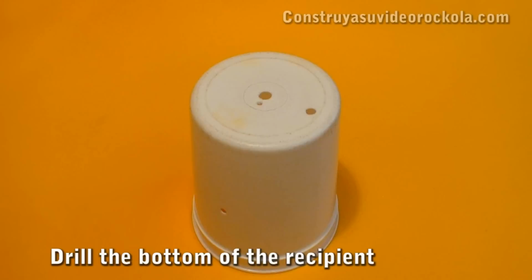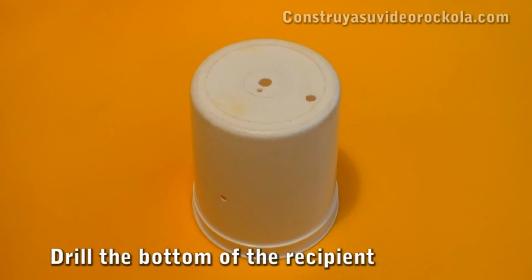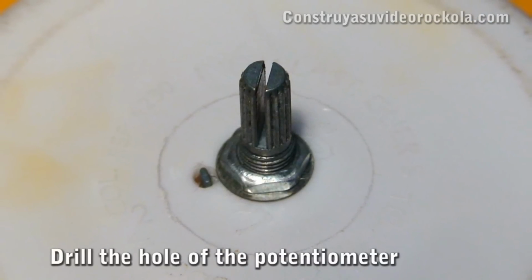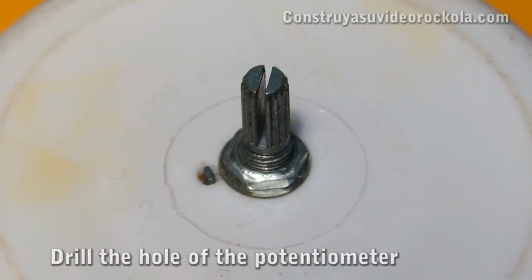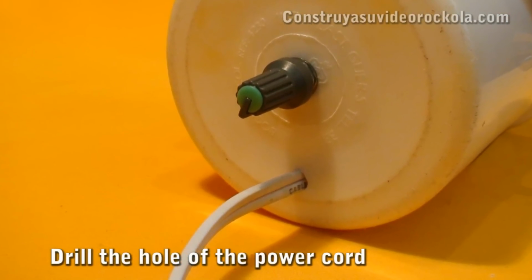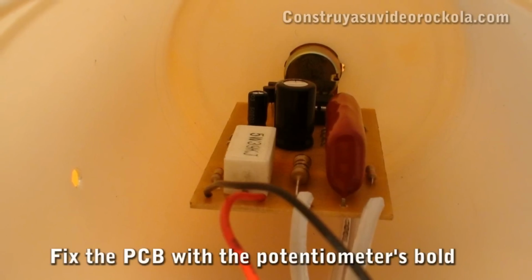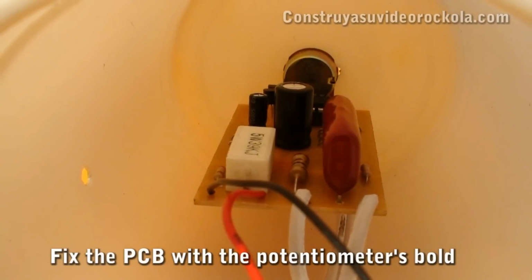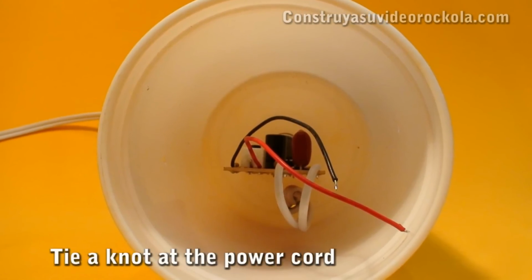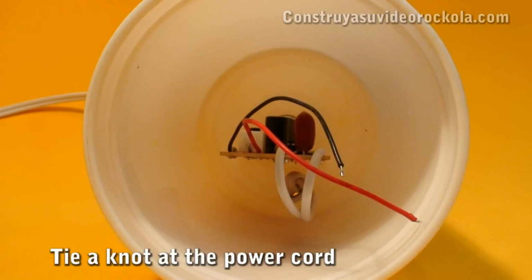Now comes the installation of the oscillator circuit in the ice cream jar. Three holes must be made in the back, one for the potentiometer shaft, another to fit the pin, and at the bottom another hole where the power cord exits the circuit. The card is installed by securing the pot with a nut and washer. It is important, before passing the power cord out, to tie a knot so that when we pull on the cable we do not damage the circuit.